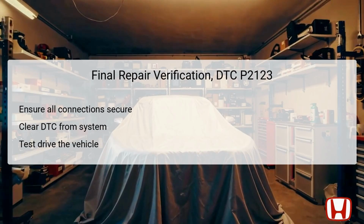This will eliminate any prior faults from being read and allow for an accurate assessment of the system. Finally, conduct a test drive of the vehicle under various driving conditions to confirm that the steering and acceleration respond normally without triggering any check engine lights. This final test will ascertain that the repair performed was effective and the vehicle is operating as intended. Ensuring these steps are followed helps maintain vehicle safety and performance.